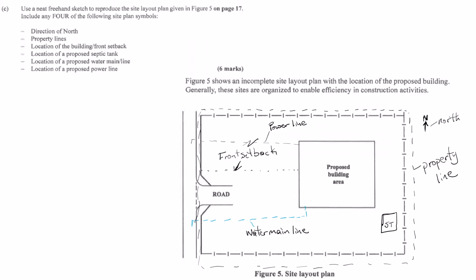Precisely. And to make it clear, site plans use standard symbols. You'll almost always see an arrow marked N. That tells you which way is north. Essential for orienting the building. Okay. Property lines, the legal edges of the lot, are usually shown as dashed lines. And the front setback, that's the minimum distance the building has to be from the road, often shown as a dotted line. Right, defining the legal space and where you can actually build.